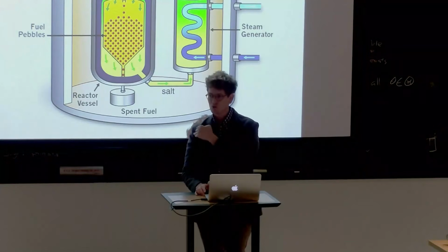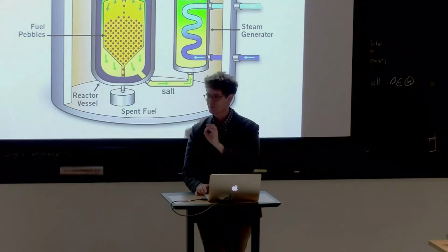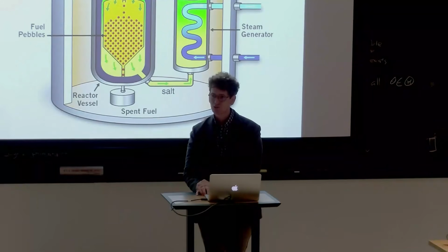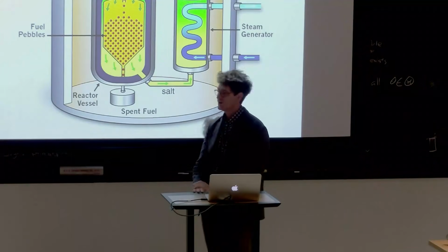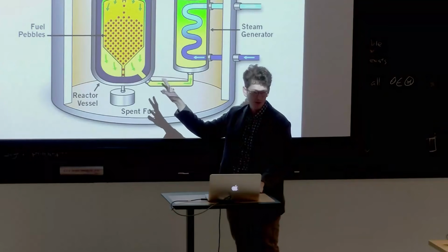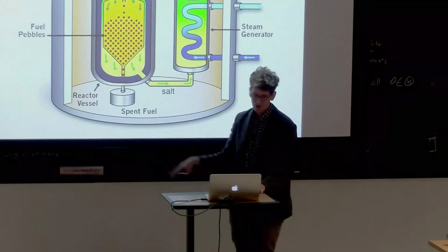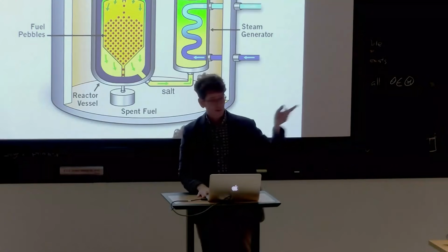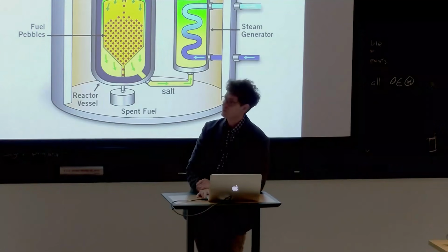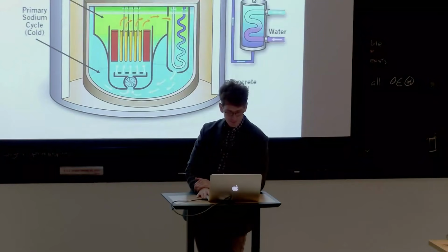It will just corrode anything very rapidly because you can just move electrons around and chemically facilitate corrosion. So these reactors are also being designed. There's a group here in our department at MIT that is a big fan of these, but again, also has issues. FLiBe is also, incidentally, the coolant inside the SPARC fusion reactor, and all these same problems exist with FLiBe in that application as well.